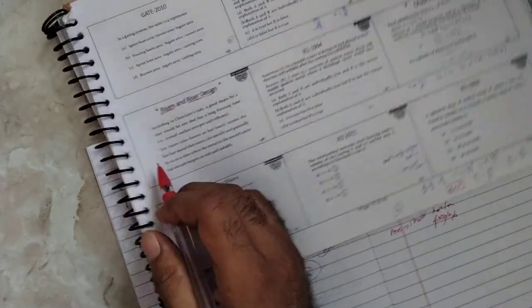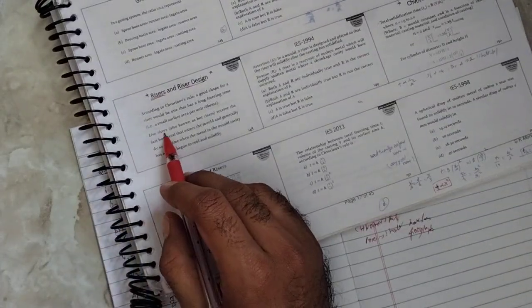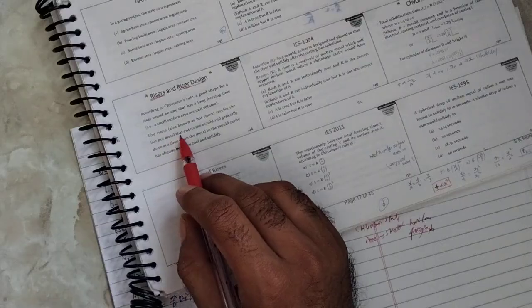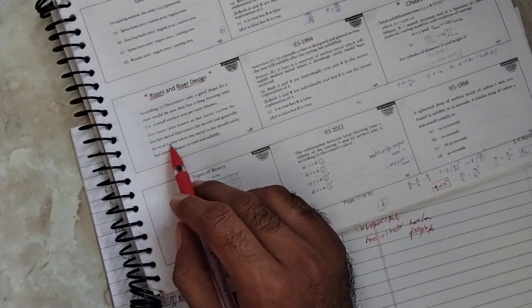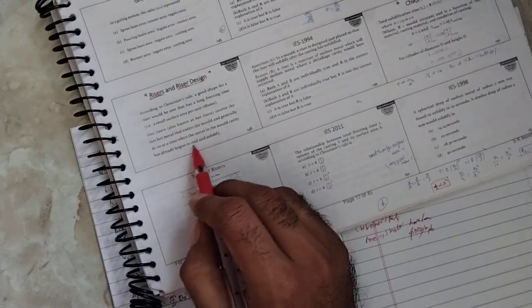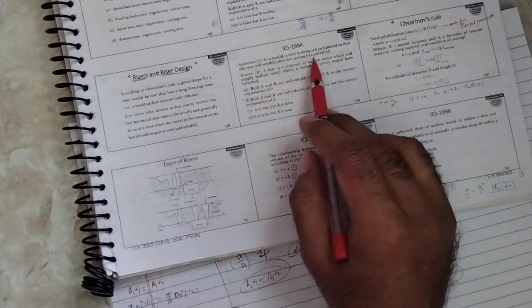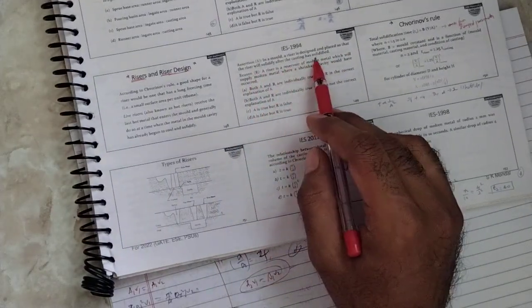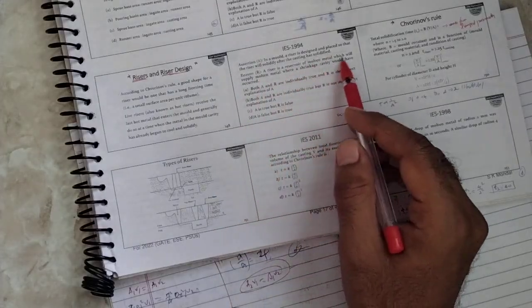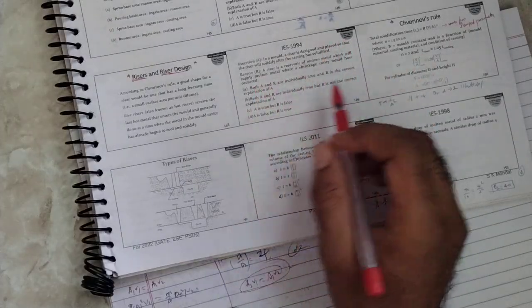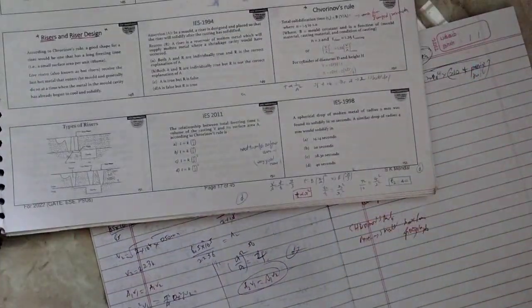Okay, so this next thing is the riser, also known as a hot reservoir. It receives the lost hot metal that enters the mold, and generally does so at the time when the metal in the mold cavity has already begun to solidify. In a mold, a riser is designed and placed so that the riser will solidify after the casting. A riser is a reserve of metal which will supply the metal where the shrinkage cavity would have occurred. Okay, so Chvorinov's law is this one.